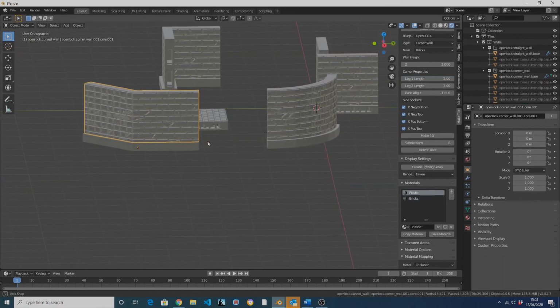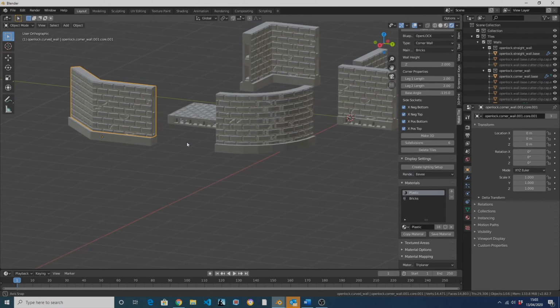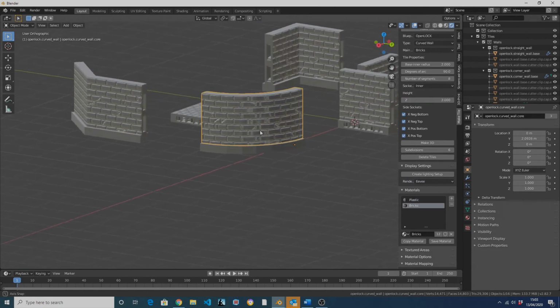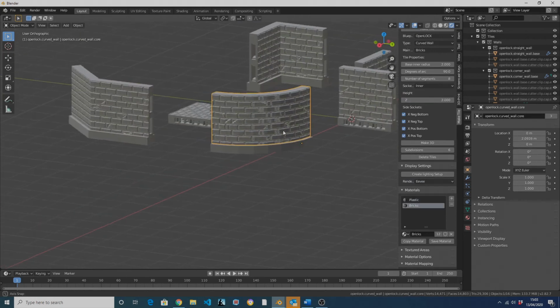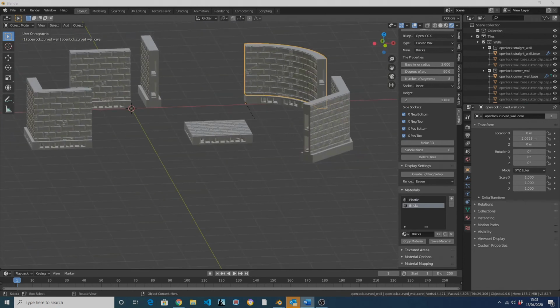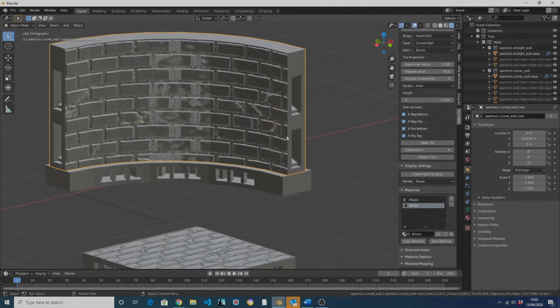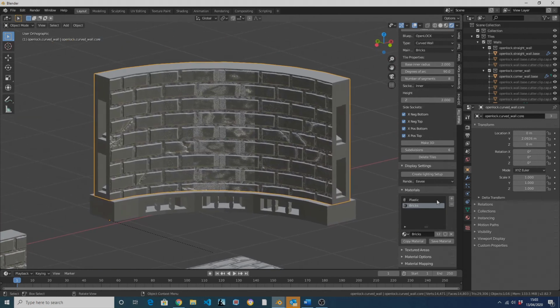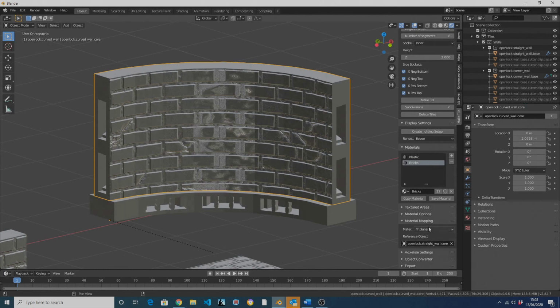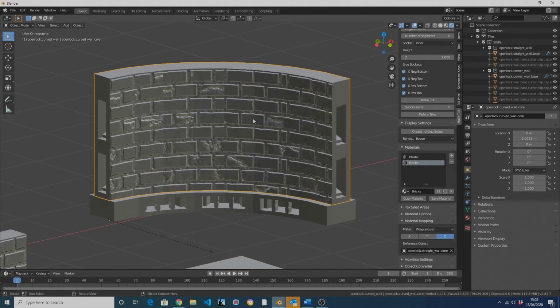There's also one set of tiles that behave rather strangely. Because of the way they're created, materials applied to the curved wall and curved floor tiles won't display correctly in the material preview mode if you're using triplanar mapping or the wraparound mapping. I'll cover what's going on here in a future video, but for now just be aware that when you're using the curved wall or floor tile types, you'll need to make it 3D to see what the material will look like when it's exported.